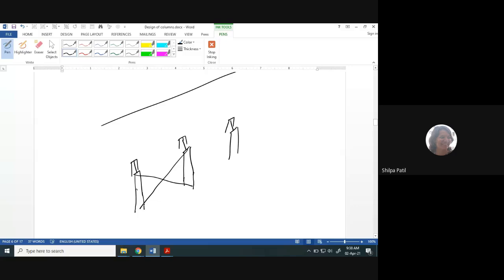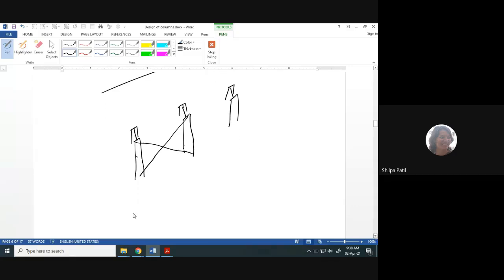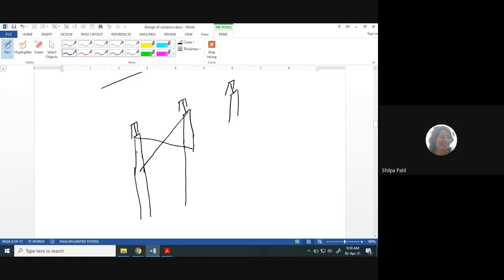The column is further having a height below this also. So the column is actually having a certain height like this. Okay, so the bracing system is provided like this. So actually, when a buckling of a column takes place, as it has a support at a mid height over here, the column will buckle only this part of the column will buckle like this.